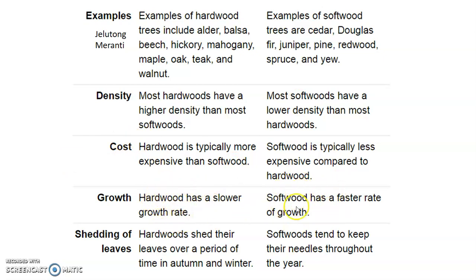The other reason is that hardwood grows at a slower rate, whereas softwood grows faster. So if you were to use hardwood as glulam or cross-laminated timber, it means that it takes a very long time to grow and harvest the hardwood. Typically for softwood, the cycle is 20 years, meaning that in 20 years' time, you can harvest the batch of softwood for the production process. So you have a turnaround cycle of 20 years. But for hardwood, it's typically more than 20 years. So it may not be so easy to have a sustainably managed forest that produces hardwood all the time. But softwood is easier.